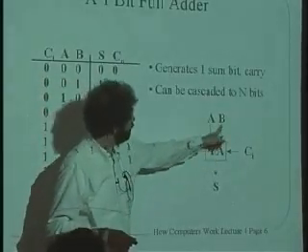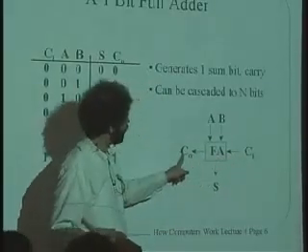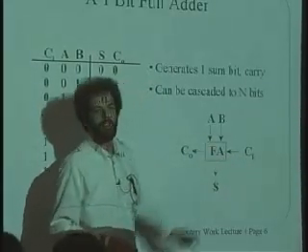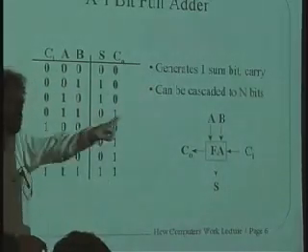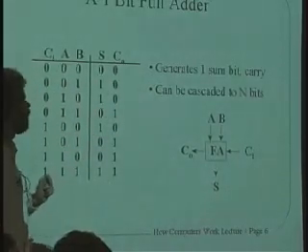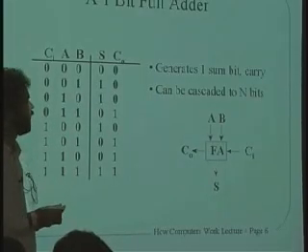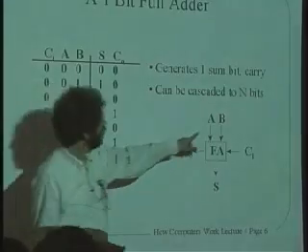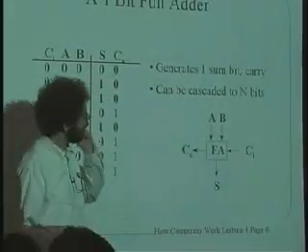A sub i comes in here, B sub i comes in here, carry in goes in here, carry out goes out here, and the sum bit pops out down at the bottom. We can describe this with a map exactly like what I just showed you over there, except luckily now we have far fewer than 2 to the 70 bits. How many bits of input do we have? 1, 2, 3. 3 bits of input. How many bits of output?